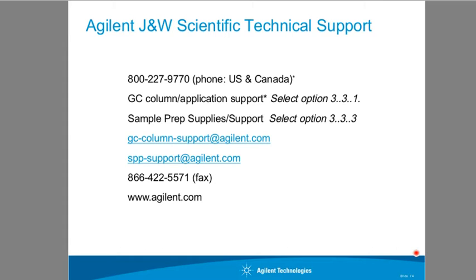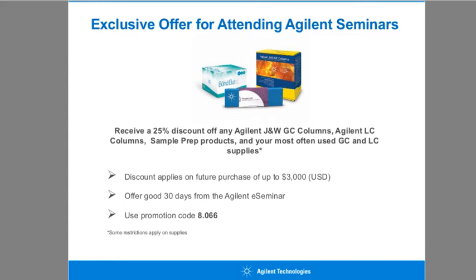Yeah, something's got to be different, and it could actually be a result of the column at that point. But what we would need to do is really compare retention times. Obviously, the oven program's the same and things like that. But what can happen is, if you put in 1 mL/min or 30 centimeters per second on your front inlet and do the same on your back inlet, your velocities through those two columns are not going to be the same. I will almost guarantee it. The system doesn't measure that.